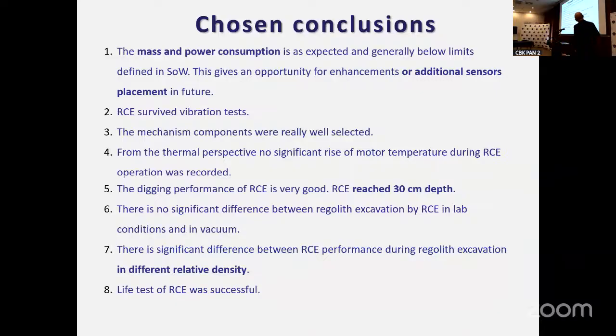I just want to say a few important elements: we reached 30 centimeter depth during testing in laboratory conditions. And we also survived the life tests. We've done almost 300 tests. This number was defined based on the FMEA analysis. And also important, we performed tests at different relative densities in the lab and then later during the parabolic flight.